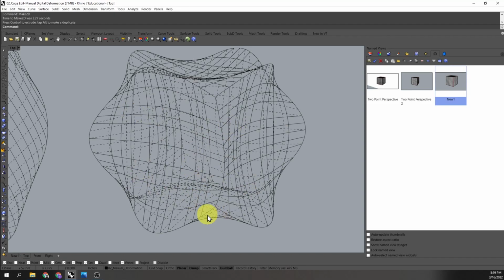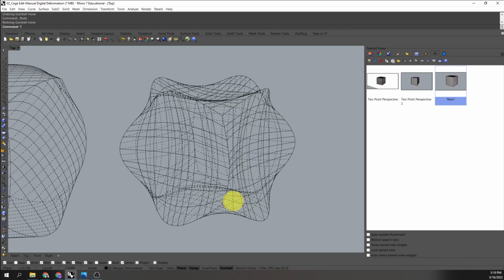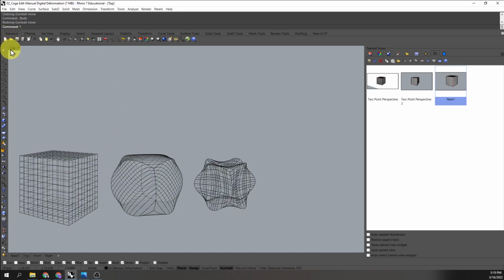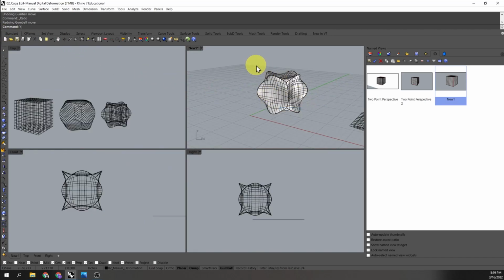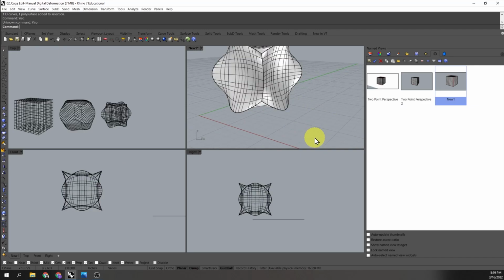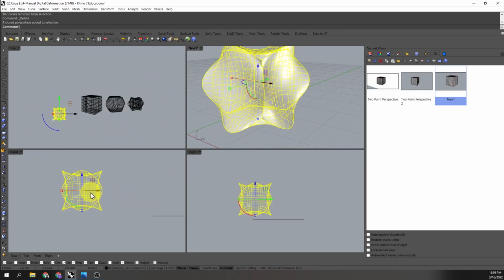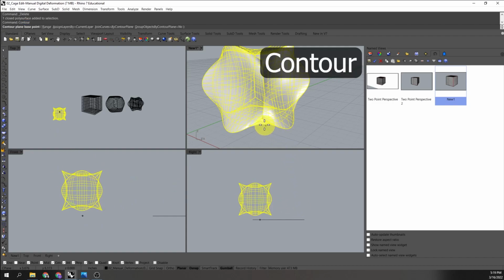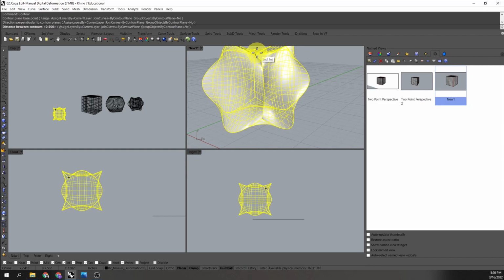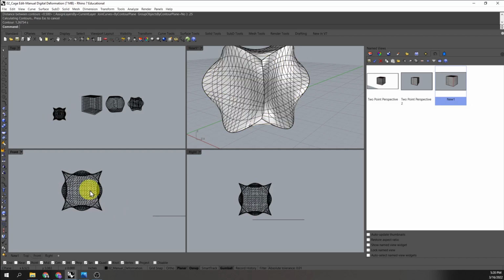Or we can use a similar method as we did with this. Let's try something like that and see what comes out. So if I focus on this, let me just select my curves. I'm just gonna delete those, and let's make some contour lines. I'm gonna do them from here to the back at, let's do 0.25 intervals, so a lot denser.